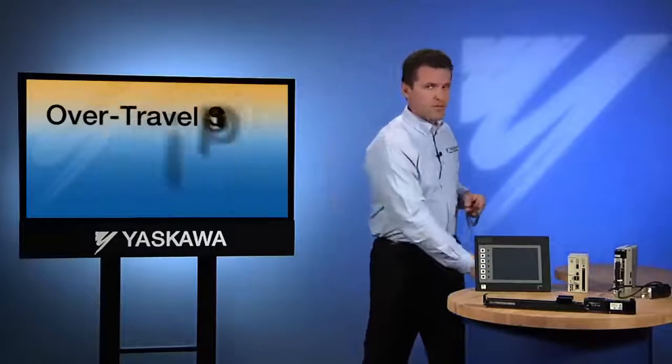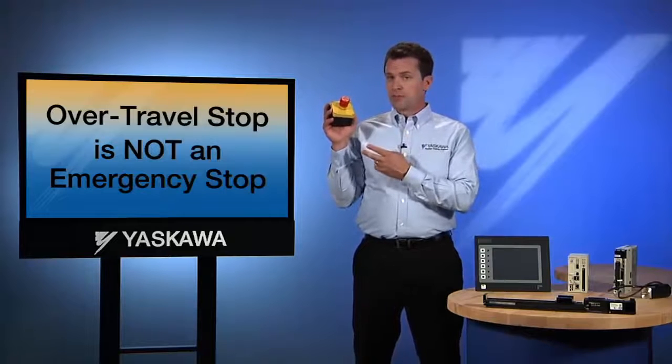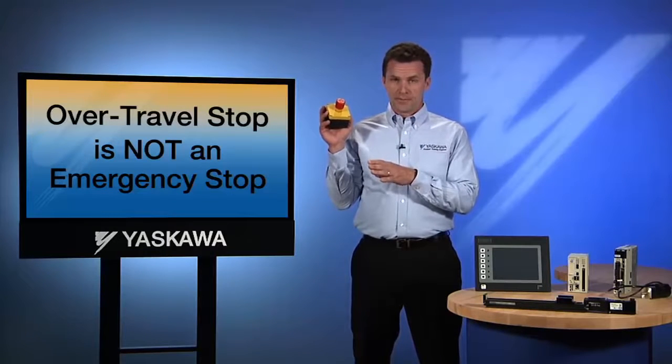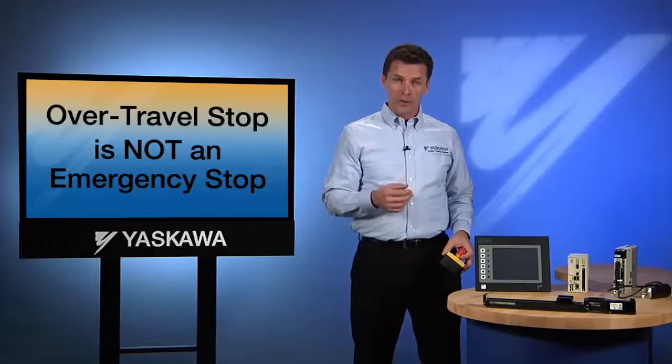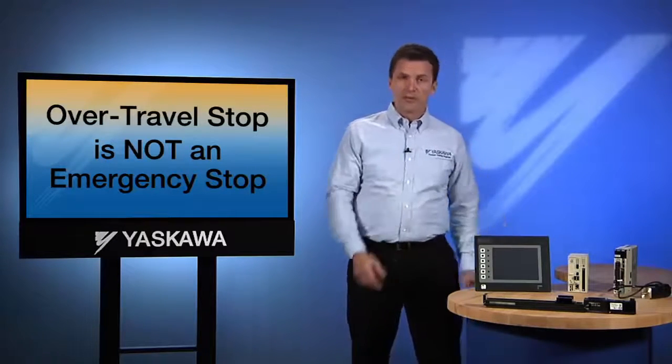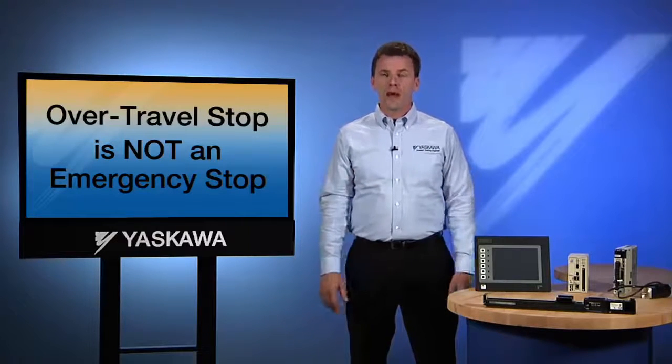So you can see that if these sensors get switched around, or if the direction of the servo doesn't match the direction of the machine, the motor might not stop at the overtravel sensor. Damage or even injury might result. It pays to remember that an over-travel stop is not an emergency stop. An emergency stop would prevent all motion in all directions. An over-travel stop is simply a quick way to stop motion in one direction. In an over-travel condition, the controller can be programmed to recover and the servo can still be moved in the opposite direction.